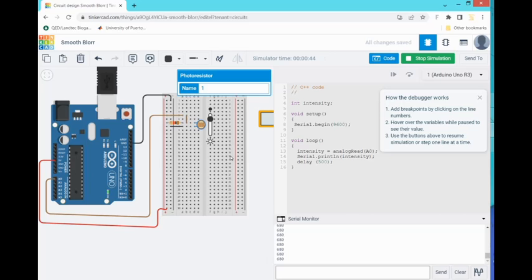Anything else? What I don't like is that the number maybe is not going in the right direction. It will confuse you, because basically you would like this number to be the highest number, indicating very high illumination. Let's work out a calibration that makes more sense to you. Like for example, let's say that 1,000 is high illumination, and this is very important, and this is where the units come, the unit that you have in the measurement, and this is where you establish them.